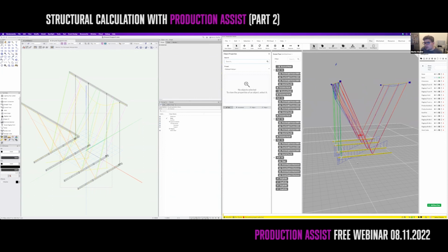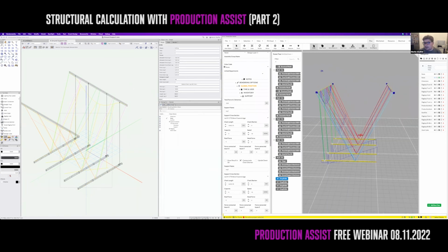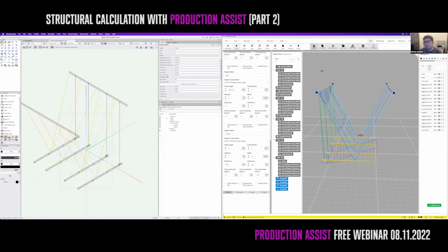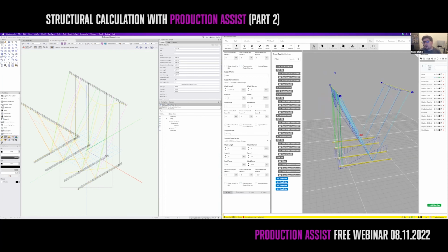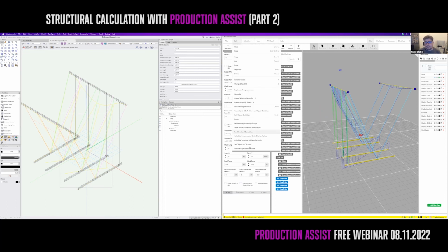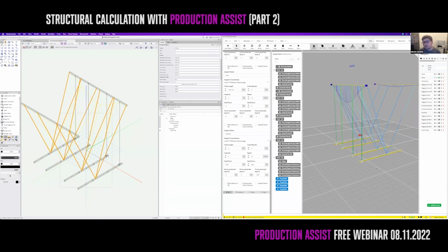So what we have for this is normally something called drop compensation. With Production Assist, you can enable the objects that should be compensated. There is a button in here which is called Compensate Chain Shorten. If I'm now selecting all the bridles that I have and disable the chain shorten compensation for them, I can run a calculation which only moves the hoists up and not the bridles. So it's an accurate calculation for this, by using selection, edit, calculate compensated chain shorten values. And this will now level our trusses in here, but will not touch the actual bridles in here, which is really easy.